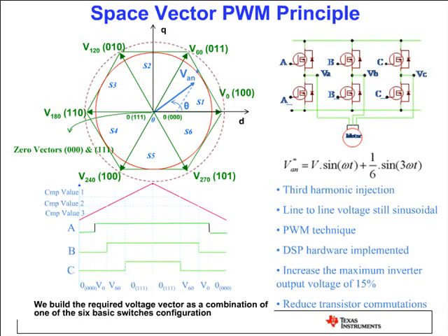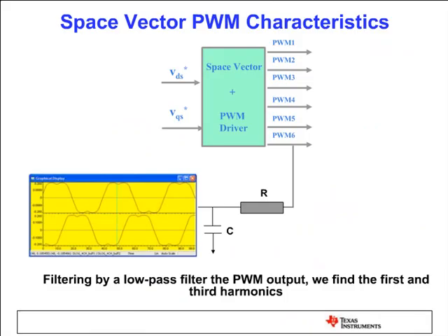The good thing about this is the low-pass filtered duty cycle waveform. It looks like sine, but not exactly sine. It's because we inject third harmonic, indirectly. So what we do, we taper, we cut the top of the sine. If you look at the Fourier expansion, we still have the fundamental component that we need to spin the motor. The good thing about this waveform is the third harmonic does not have a path on the Y-connected or delta-connected motors, so it doesn't hurt the system. So what we are doing, we are saturating or tapering the peak of the sine.